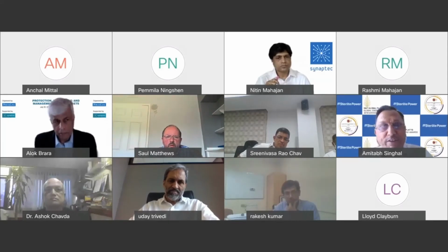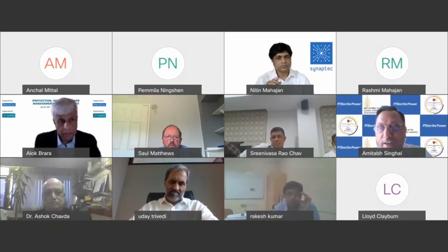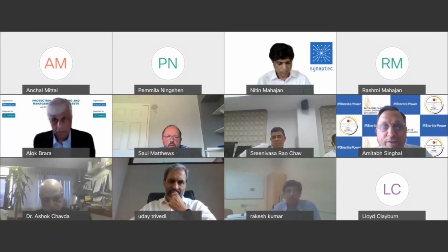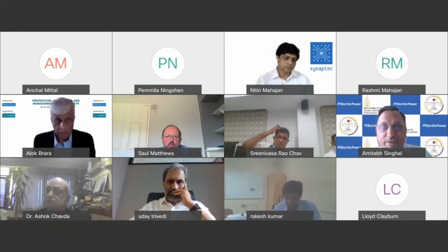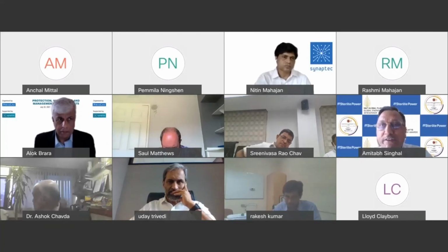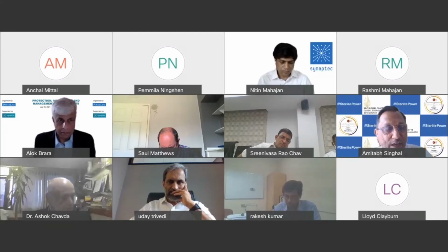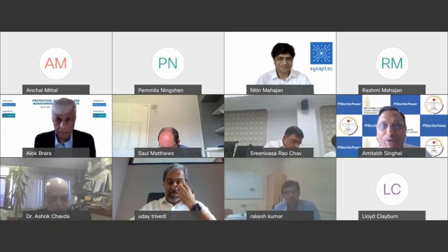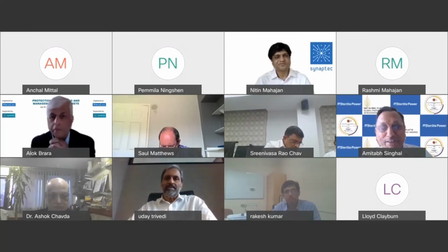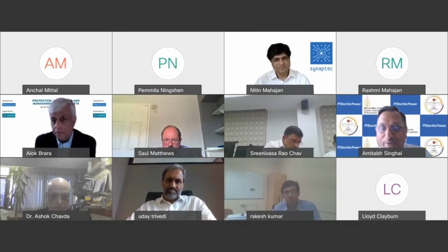So that is number one. Number two, something which is very relevant is all this climate change. Very recently, we have seen some big weather events on both of our coasts. And also the wind zones in the country have been revised as per the Indian standards, which renders a lot of the existing transmission assets liable for failure in case of such weather events, because they have been designed for the earlier wind speeds.